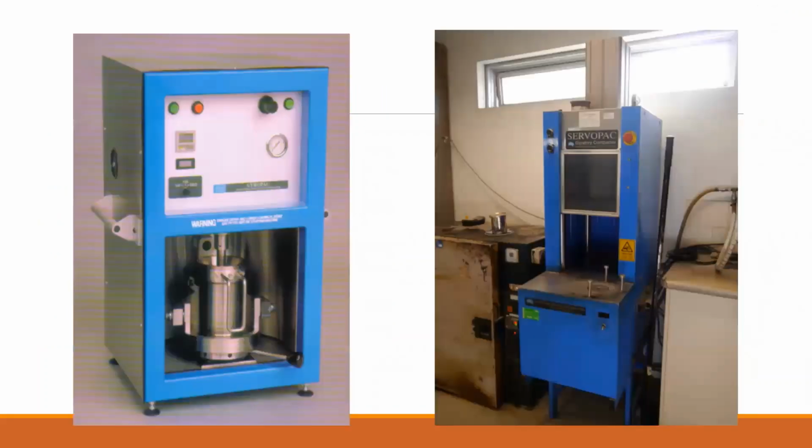This is the machine that we are going to use. And as you see here, this is our cylinder. So you can see this rod which is applying the vertical force. The cylinder is rotating with the set angle which is 2 degrees. And we set the pressure, and you can set the pressure here, and you can see that reading 240 kilopascals here.